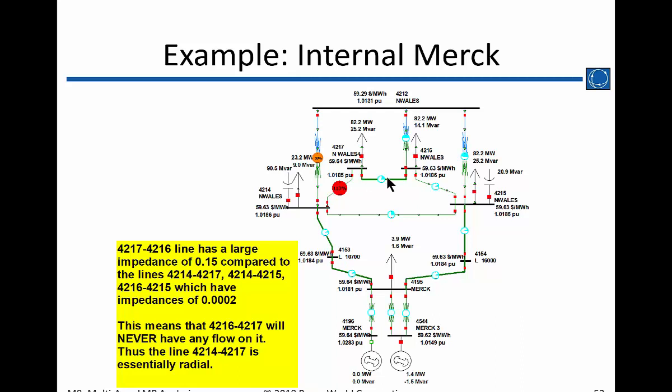Not much flow is going between here, and you have a load at this bus. So that load mostly has to be fed on this line. So it's causing an overload here because of the limit on this line and the value of this load. So you could ignore that limit perhaps because it's effectively radial. Or you can just open this and then ignore it.